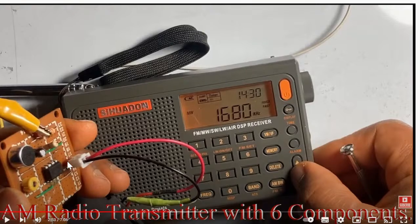And then we have a resistor. Actually, we have 2 resistors, but this resistor works with the capacitor to bias and produce the frequency we're going to look at in this transmitter. Then the other resistor works in conjunction with the microphone and capacitor for the audio input. So we're going to analyze how this works.